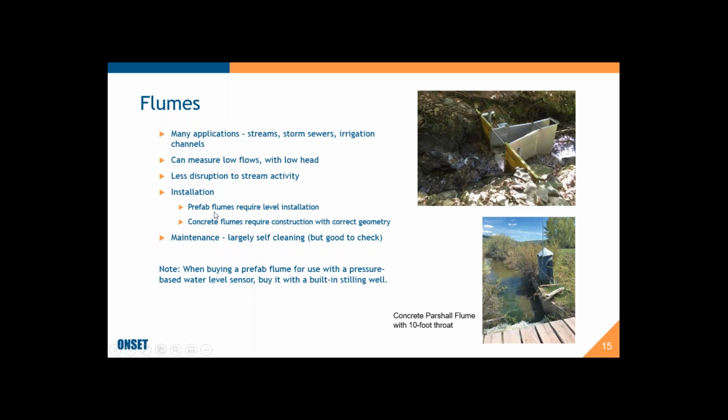Installation for flumes is a little bit more work. As you can see here, you've got to create a little bit of a wall, and you got to make sure it's level when you put it in the stream. This is an example of a prefab flume, which is a great way of measuring stream flows.